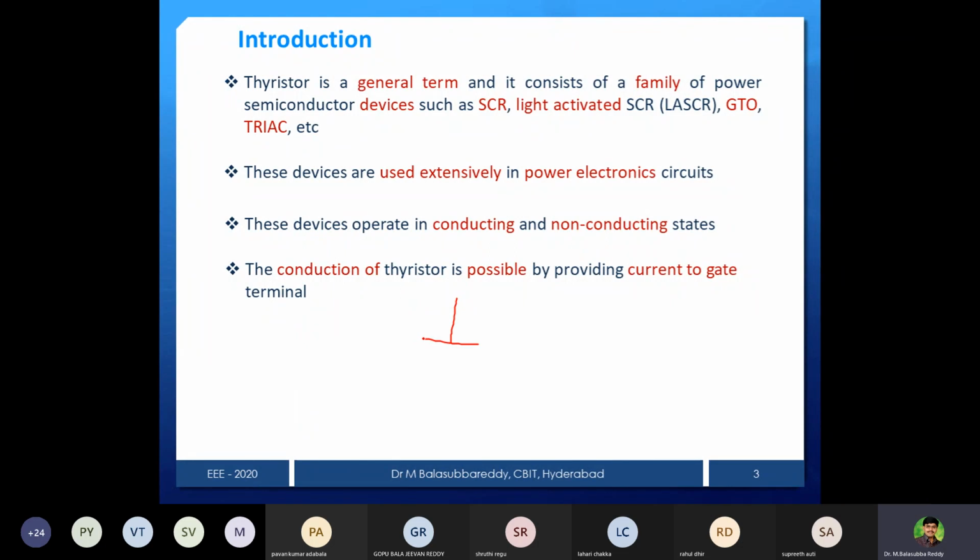Like we can see, this is a thyristor. Anyhow, the turn on methods will come once again. Let's see, this is the symbol for the thyristor. Now, what they are mentioning in the above statement: if you pass current to the gate, the gate current, IG, there will be limitations also, a minimum limit and a maximum limit.